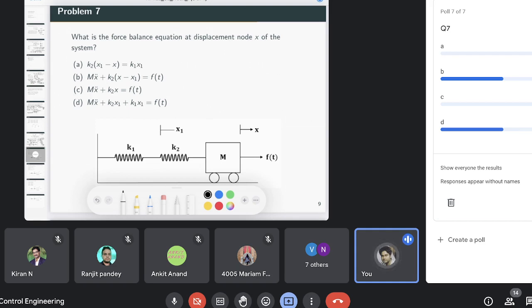So you have a mass spring system. So you have 2 points of displacement. One is here and another is at this point. Okay, at this connection point of these two springs. So for this point x, so you can write this equation. So again following this basic mechanics equation, you know how to write. At every point you have to have this summation of all forces should be 0. That's all. Okay, so this is the basic things you have to write.